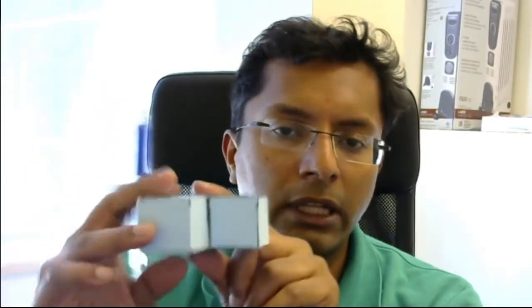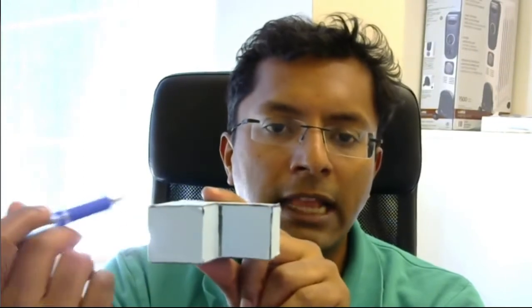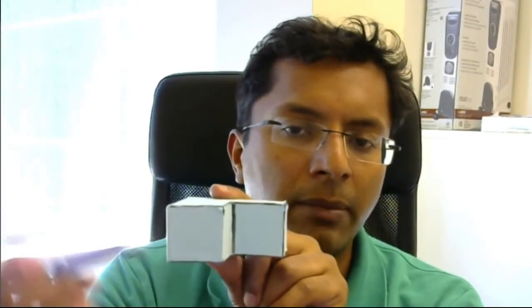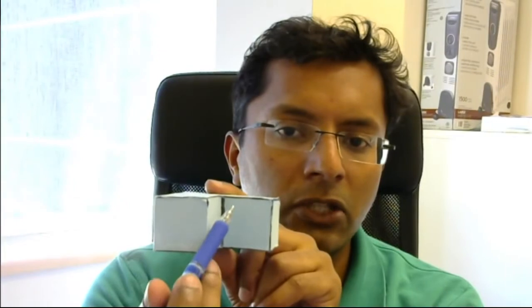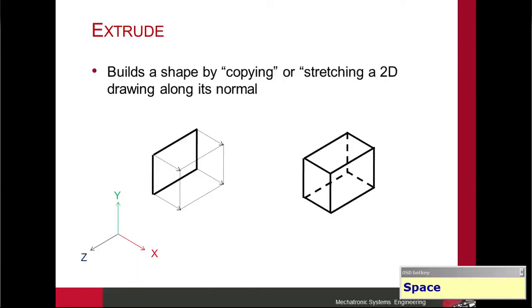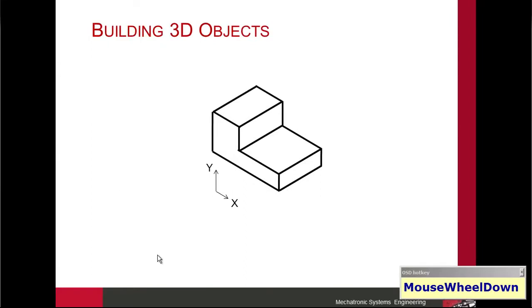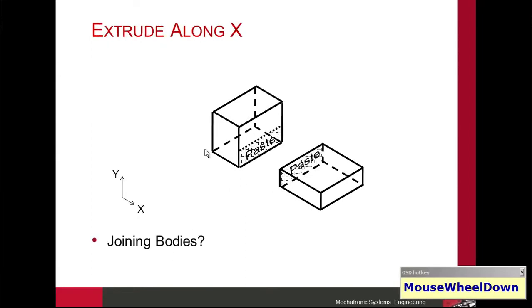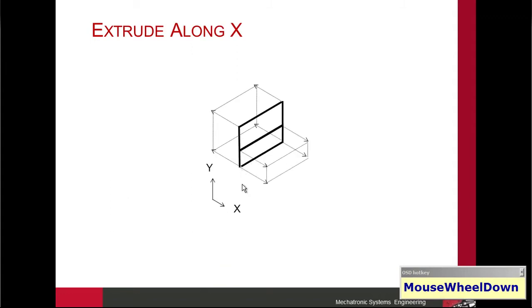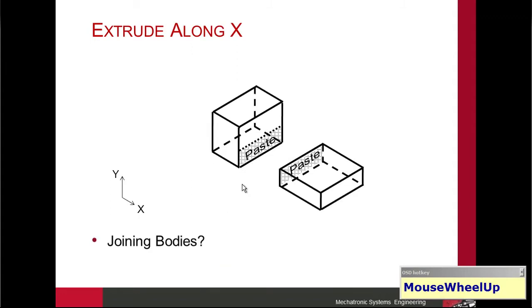The second one is to see if we can do it slightly differently. Finally, we look at this view, known as the top view, and think about creating this particular shape and then extruding it this way, and then this one a little bit this way. This is what we're going to focus on right now. To illustrate, this is a 3D object. I'm going to create the left shape and then paste this shape onto this face. The next one we'll do is extrude it along two separate directions.